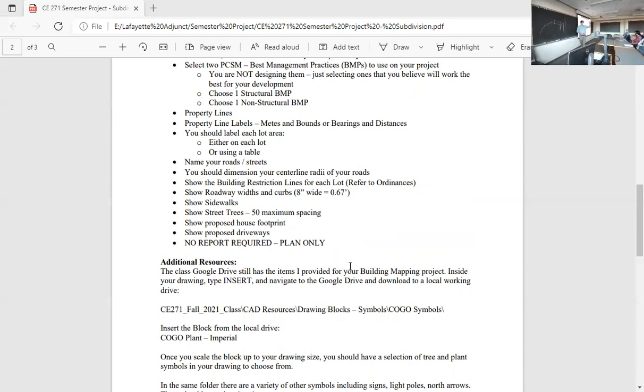Driveways. Can driveways be inside of building restriction lines? That's a little. They can be inside yards. How close do you think is a good distance to stay away from the property line with your driveway? Think putting it right on the property line is a good idea? 6 feet, 10 feet. I like those numbers. I wouldn't go any smaller than 2 feet. I wouldn't go any less than 2.